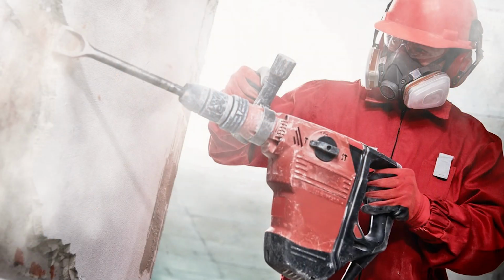Next, second one, let's talk about dust and fine particles. That would be like concrete dust, drywall dust, or anything that may contain particles such as silica. And the hazard is dust can irritate or damage the eyes and may contain hazardous materials like silica. The mitigation plan would be elimination. Use prefabricated materials to reduce on-site cutting or grinding.